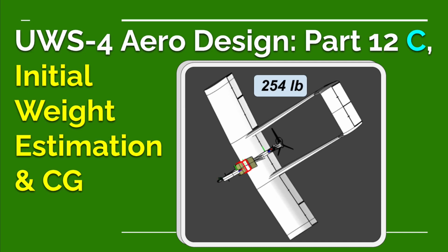In parts A and B of this series, I decided to use some weight estimation equations for the wing, horizontal tail, and vertical tail from Dan Raymer's book, Simplified Aircraft Design for Homebuilders. In part A, I just looked at the equations as they are out of Dan's book. In part B, I worked on some modifications to try to make them a little more applicable for ultralight airplanes. In particular, that's because we have a minimum gauge problem, which modifies the surface area component of those equations.